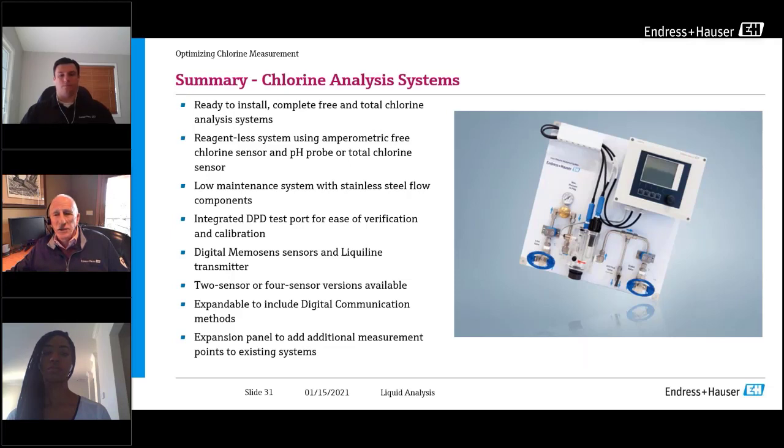Unfortunately, given the nature of these devices and the components, this device does not have NSF approval, which means the water coming off of this cannot really go back into a drinking water supply. Now, if it's wastewater and you're sending it out to the aquifer, that's a different story. That you could put back into the process. But generally speaking, in a drinking water type of operation, the water leaving the system would have to go to drain because it doesn't have NSF approval on the components.